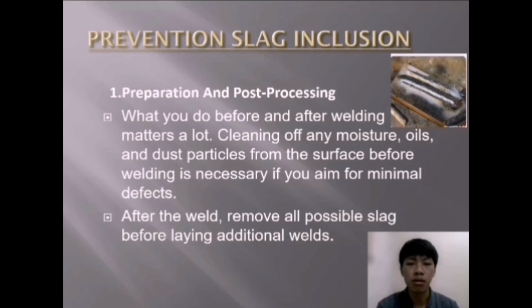The prevention of slag inclusion is preparation and post-processing. What you do before and after welding matters a lot. Cleaning off any moisture, oils, and dust particles from the surface before welding is necessary if you aim for minimal defects. After the weld, remove all possible slag before laying additional weld.